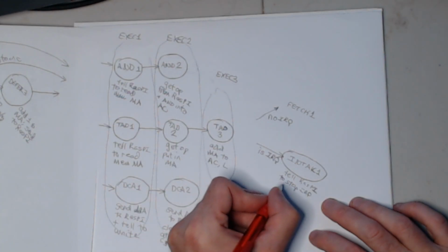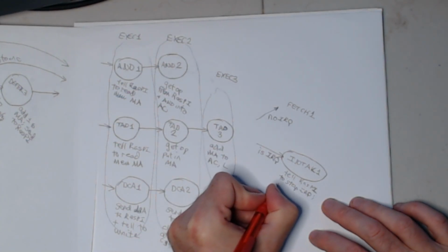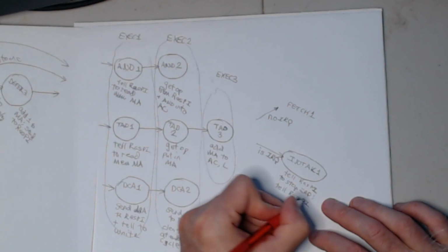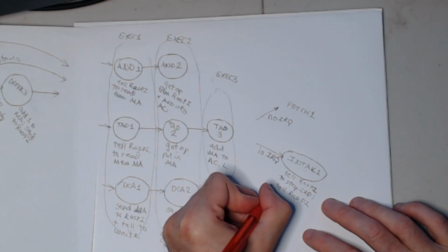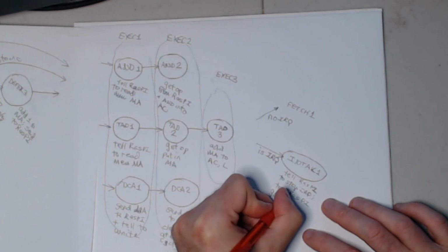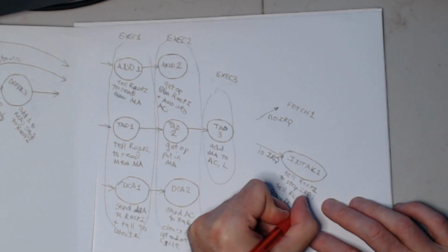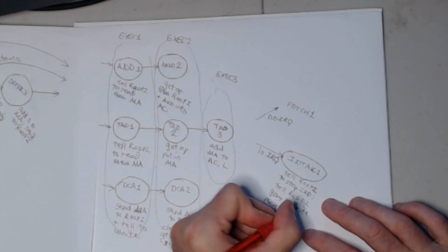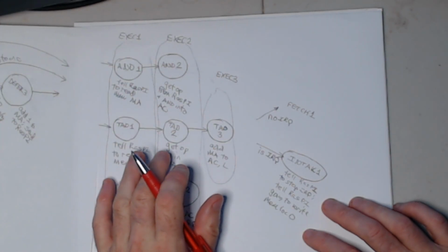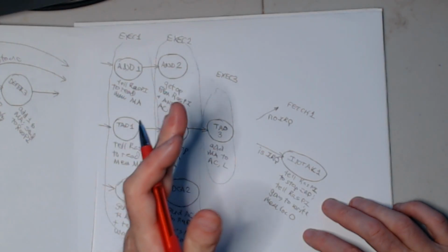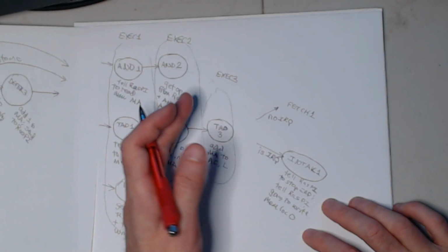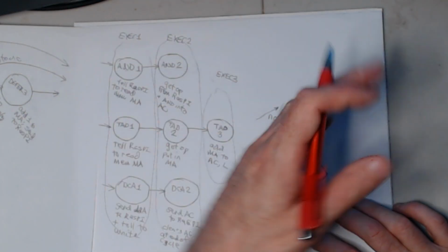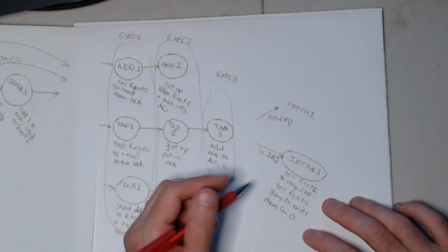It's also going to tell the Raspberry Pi that we want to write memory location 0. So it sends an address of 0 to the Raspberry Pi, tells the Raspberry Pi we're going to write memory, and it also tells the Raspberry Pi to stop requesting interrupts, because you can't keep requesting interrupts every cycle or you'd never get out of there.